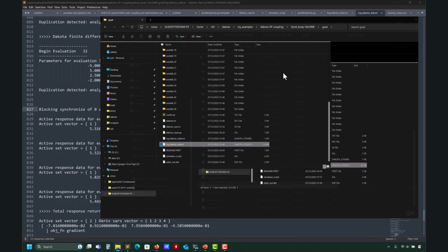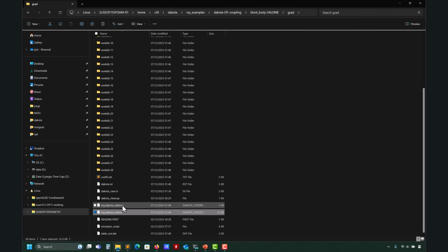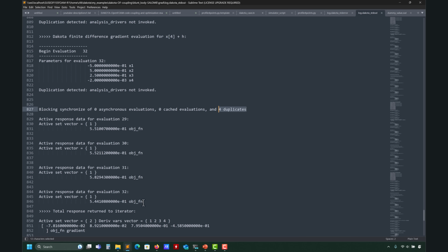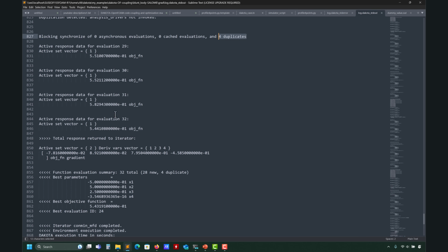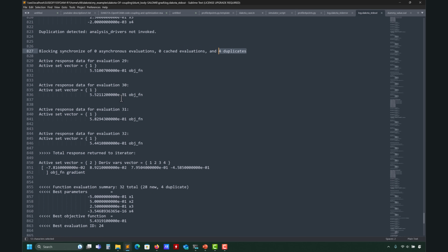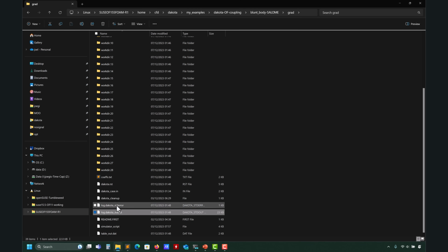Talking about that information, we have the files, and then you have this RST file. This is the restart file, and in this file you also have all the information of whatever happened here. So in the next video, I'm going to show you how to interrogate that restart file and also how to look for information. This is also the next step when it comes to failure capturing.